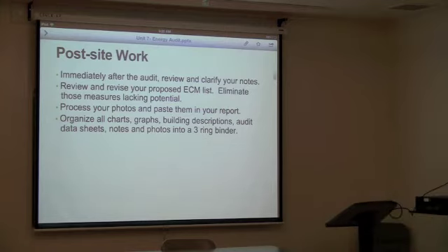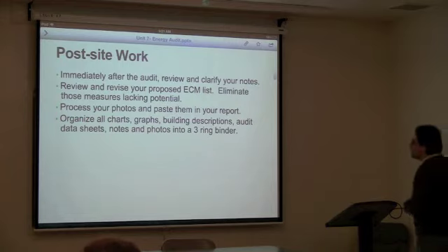Specifically, if it's an electrical motor with a fan attached and it's rotating, I take a video. The reason is that when you look at the video later, you will see if there are deficiencies, if the fan is wobbling, if the belts are not working correctly. Those are all sources of energy losses.